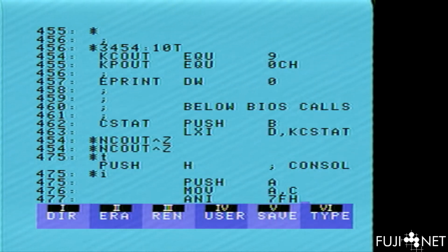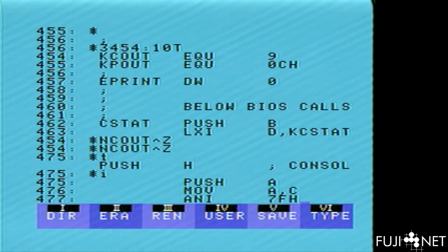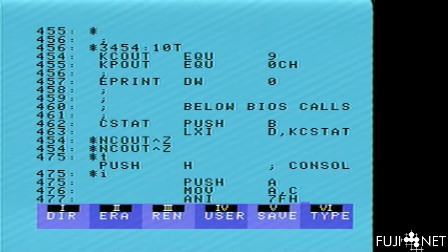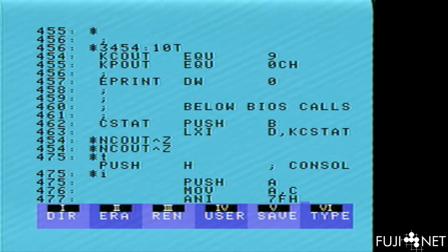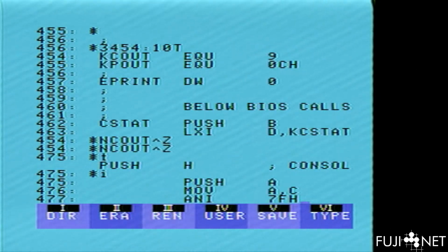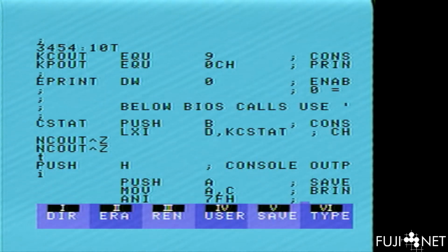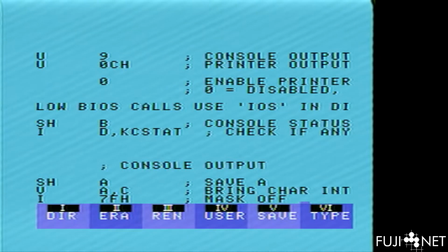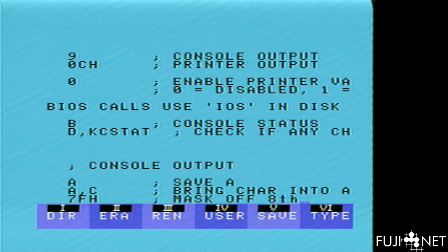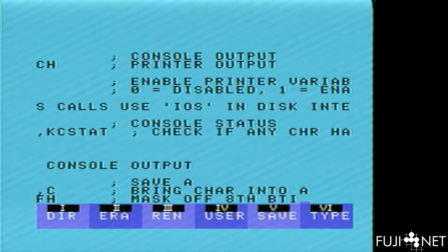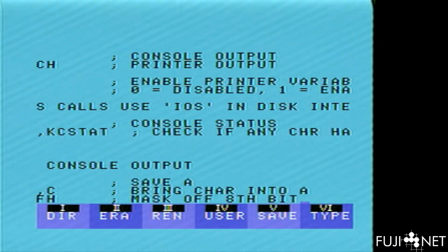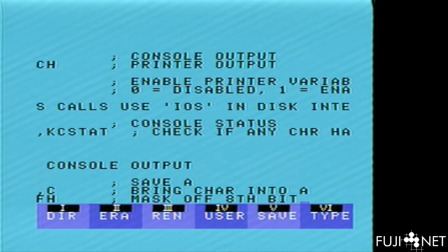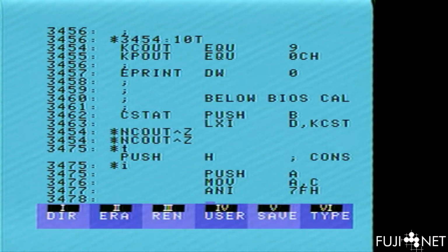We do this by saying that we want to AND this with 7F. 7F is essentially the bottom 7 bits set and the topmost bit set to 0. And for the sake of consistency, I'm putting my comments in caps, as well as my changes for instructions.